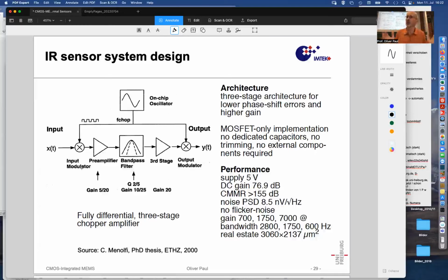And so how do people do that? If they have a signal that is in this lower frequency range where flicker noise is important, they just chop it, and by chopping it, they produce a signal that is then at higher frequency, because the chopped signal consists of sinusoidal terms that are above that frequency corner if that chopping frequency is high enough.